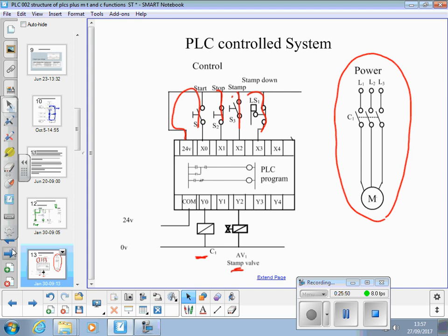If you want to make changes, you've got in your notes. I haven't got anything. If we push this button, we've got a problem. It's not always putting the lid on fully because it's making a limit switch and the cylinder's going back up again before the lid is fully home. We want to add a little time delay in so the cylinder goes down, hits the limit switch, waits half a second.